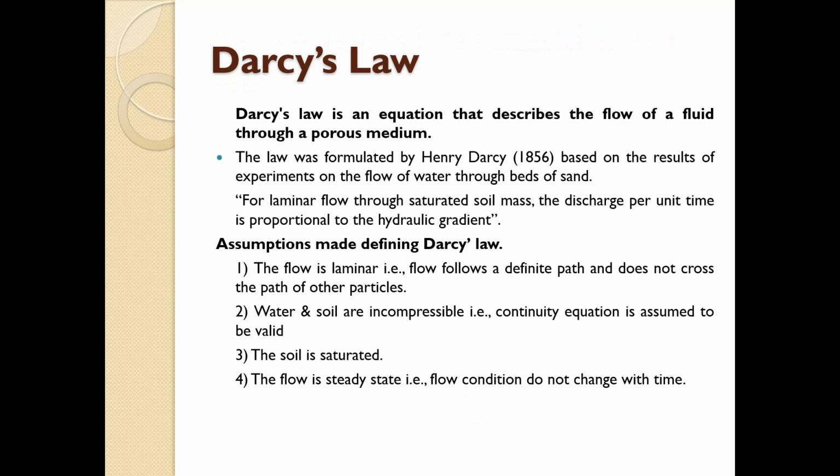Then Darcy's law. Darcy's law is an equation that describes the flow of fluid through a porous medium. The law was formulated by Henry Darcy in 1856 based on the results of experiments on the flow of water through beds of sand. For laminar flow through a saturated soil mass, the discharge per unit time is proportional to the hydraulic gradient. So this is Darcy's law.